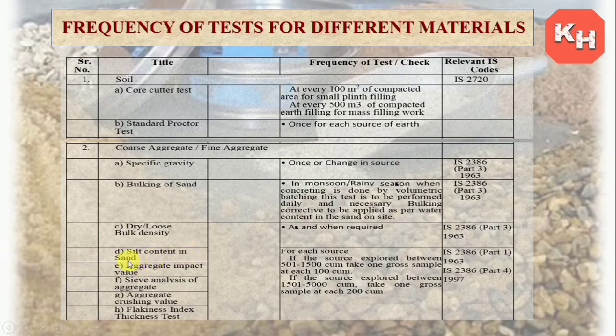Silt content in sand is done for each source. Whenever we bring sand from any source, for each source we need to take this silt content test.